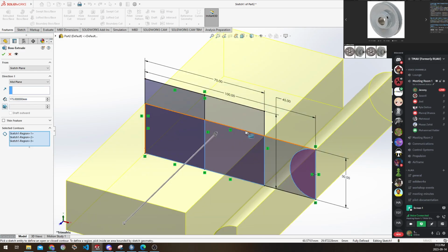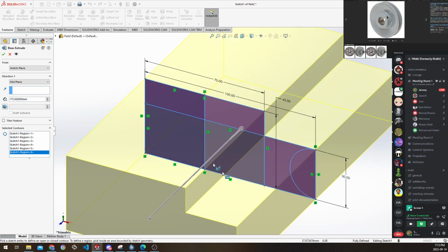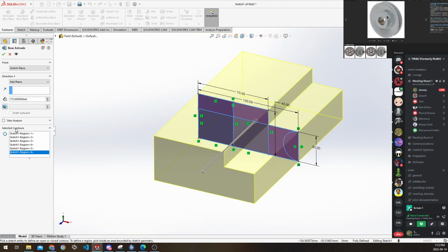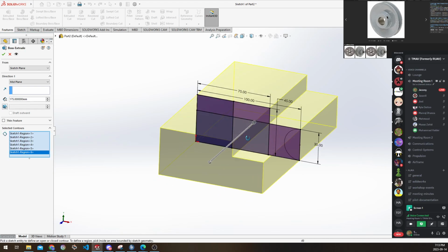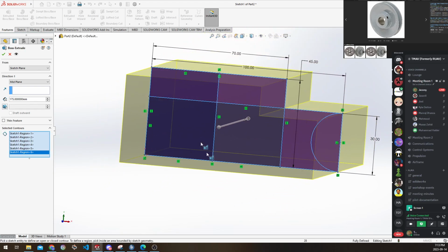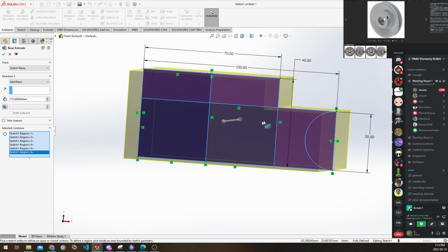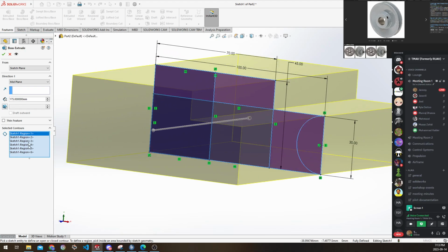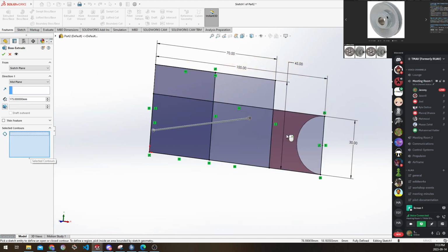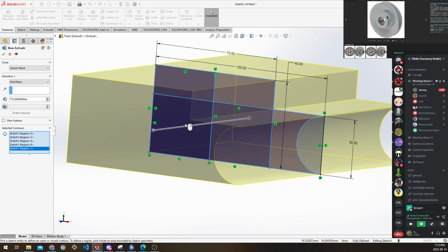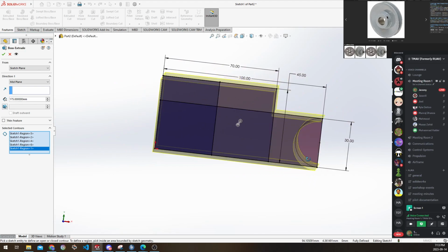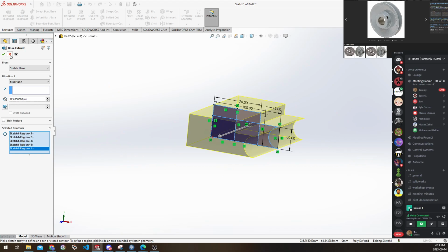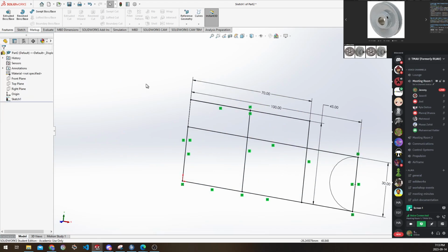You can click on a different contour, right? And this is where an example like this is really important for why this selected contour is there. This is what default SolidWorks will typically pick, but one thing we don't want is this section here to be extruded. So we're going to take these, delete them. We want to make sure we don't select that outer part. Now by manually selecting it, you can see that it doesn't extrude this section even though we drew it in. Okay, so we're going to drop out of that and look at revolve now.